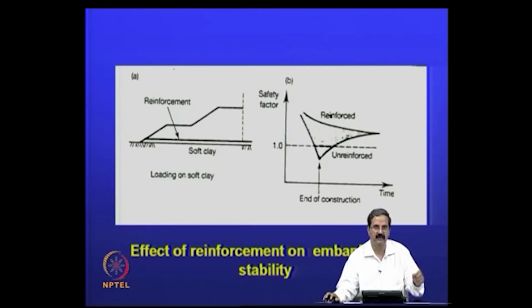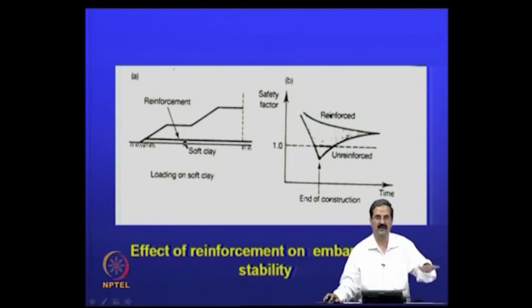Even in the construction of embankments on soft soils, we do that. We call it stage construction. This is one way of stage construction, in which you put say 1 meter of sand and then wait for it. You have some instrumentation also for that. You measure pore pressures in the field. The moment you put this sort of embankment, you have settlement gauges, you have pore pressure sensors, all of which one can install and then see exactly what is happening.